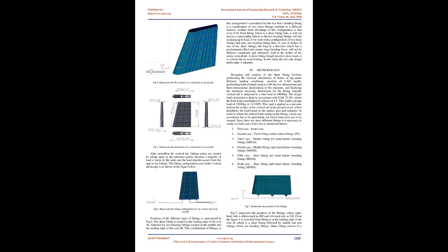According to ESDU 91008, strength analysis of the lug can be achieved when the lug is under in-plane axial, transverse or oblique loading condition from a clearance fit pin. Other ESDU methods evaluate the stress concentration due to the hole, the stress due to an interference fit bush, the endurance of a lug under repeated loading, and the stress intensity factors for cracks in loaded holes. 3. The lug analysis can be done in different methods as mentioned below.